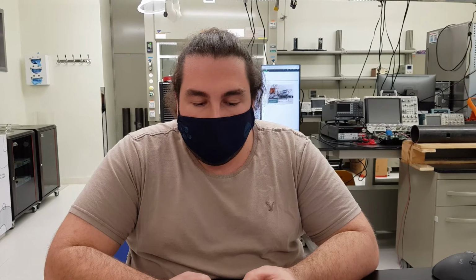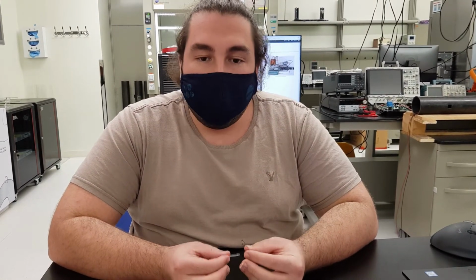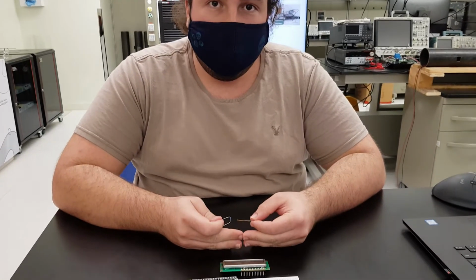In this first lab, the main objective is you're going to measure temperature using a thermistor. The thermistor is a device that changes its resistance according to the temperature, and then you're going to build a voltage divider using this thermistor and a fixed resistor, and you're going to use your PSOC to calculate the temperature and display it in an LCD device.